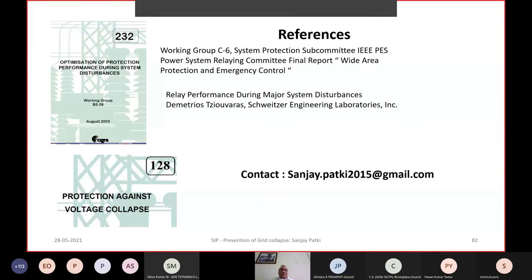In such cases, basically, you will have to go through the distance to fault measurement settings. Maybe, as I was explaining to you, some of the zero sequence compensation factors or other parameters may not be fed to the relay properly, and the way they are taken into consideration for calculations may also be different.